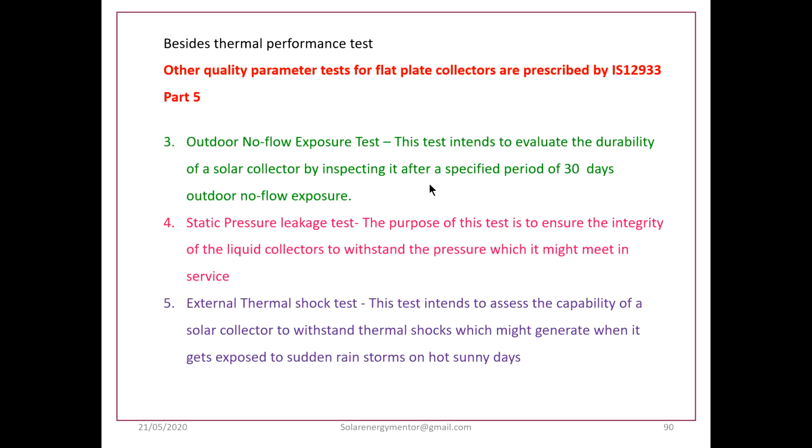Next test is the static pressure leakage test. The purpose of this test is to ensure the integrity of the liquid collectors to withstand the pressure which they might meet in service. So in the static pressure leakage test, you place a hydraulic pressure device which generates the pressure, and the outlet of the collector is closed. Then you go on increasing the internal pressure on the tubes of the collector and check whether the collector tubes sustain the prescribed pressure or not. So that is the static pressure leakage test.